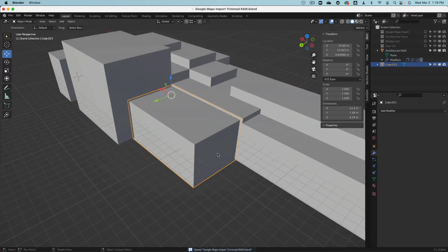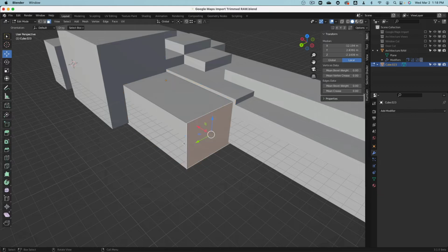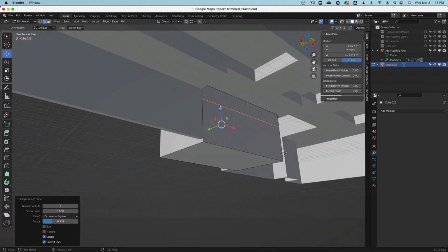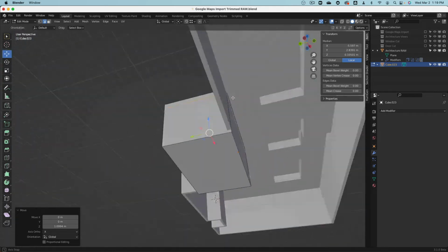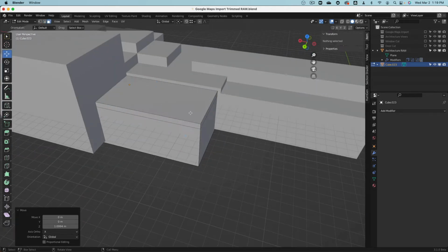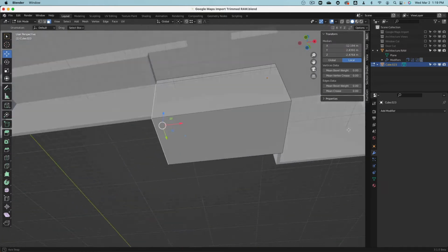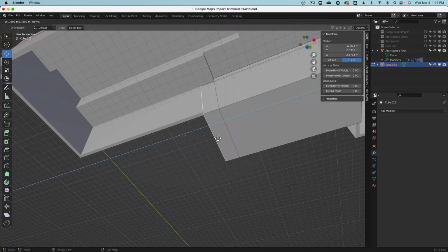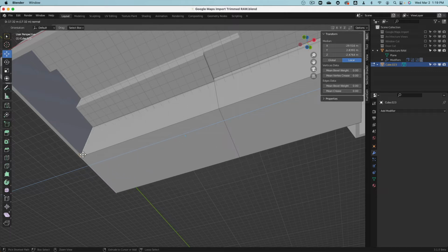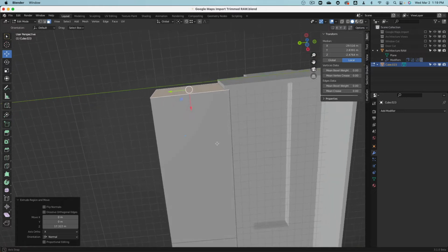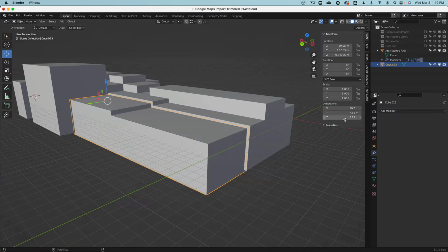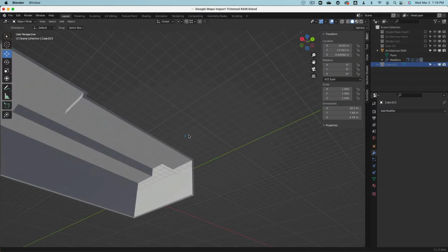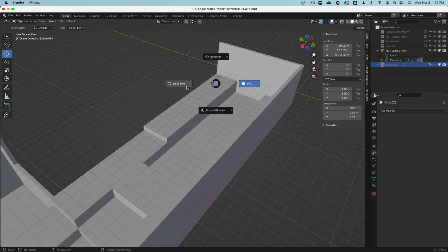So, yeah, we go to here. Edit mode. Control R, make a loop cut. Why do I do a loop cut? Because this loop cut, I move up, hold control and snap to there. And now I can select this face and E, extrude it right, hold control to there. So it stops on that wall. And leave this, hide this, and whoa, beautiful. Z and wireframe.